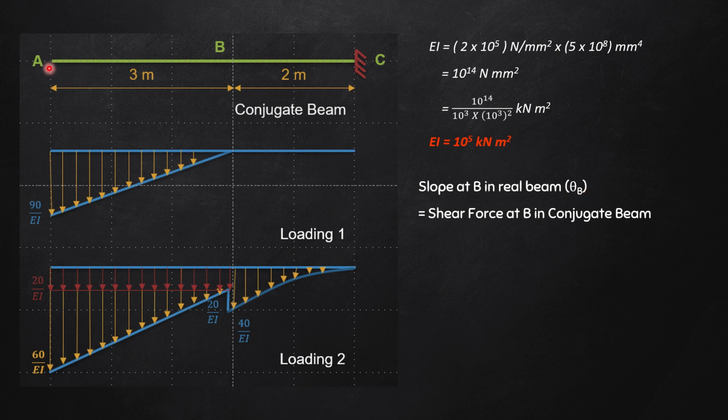Now please see, I'll take advantage of the cantilever situation here. So I will not find out the support reactions directly. If I come from left to right, here automatically I can find out the shear forces without finding out the support reactions. But what is the sign convention of shear force? Left of section, I mean, if my section is here, if this is the left of section, downward forces are negative and upward forces are positive. Keeping that in mind, let's start finding out the shear force.